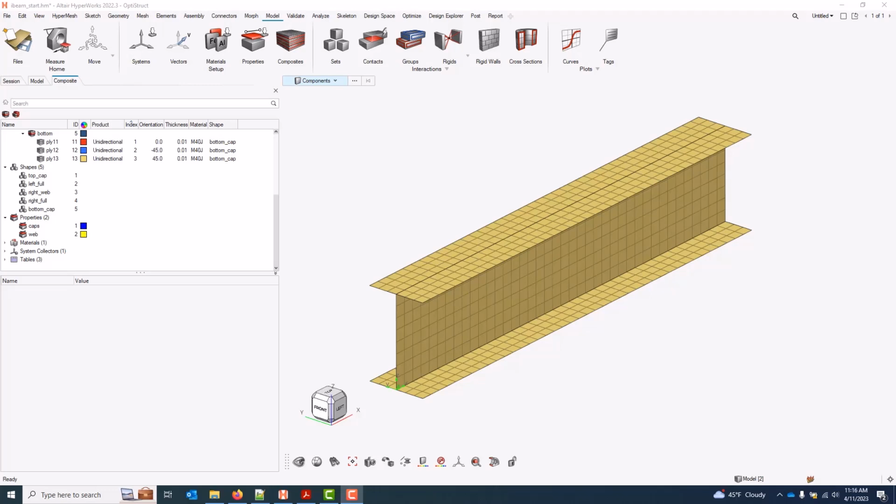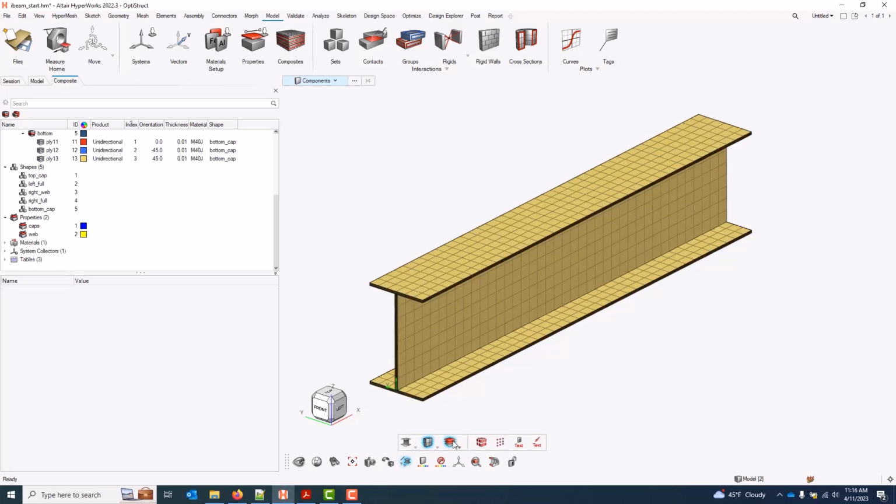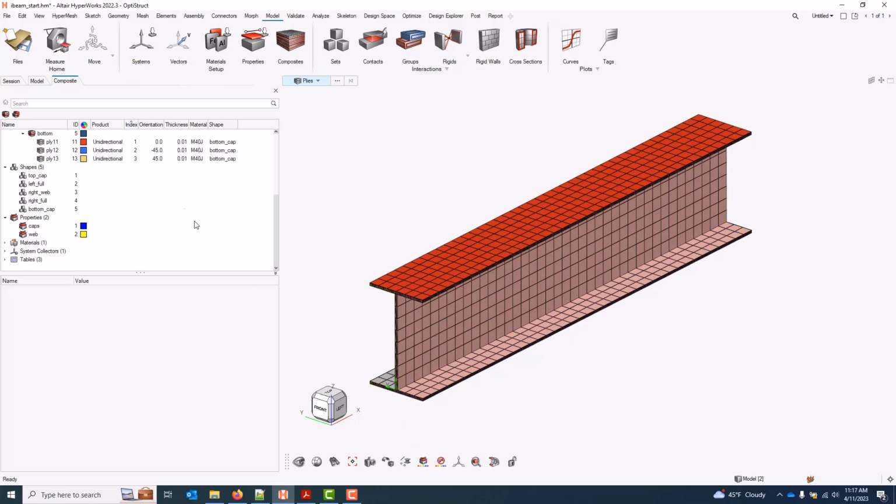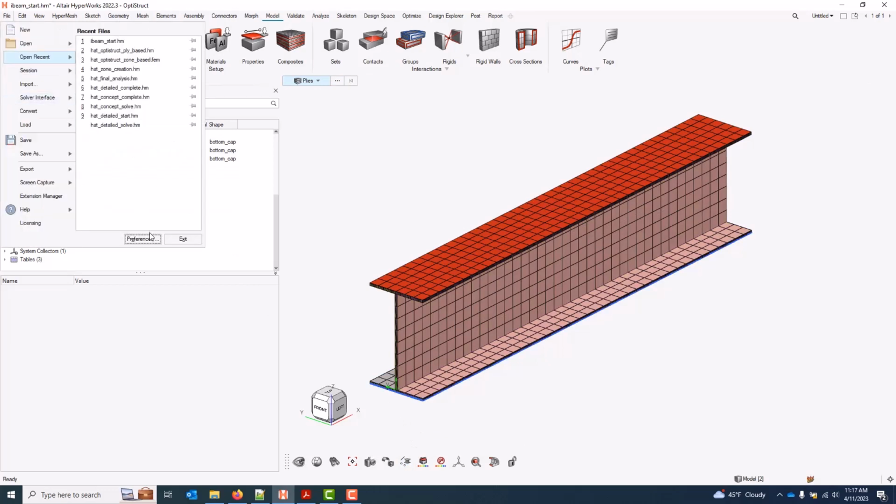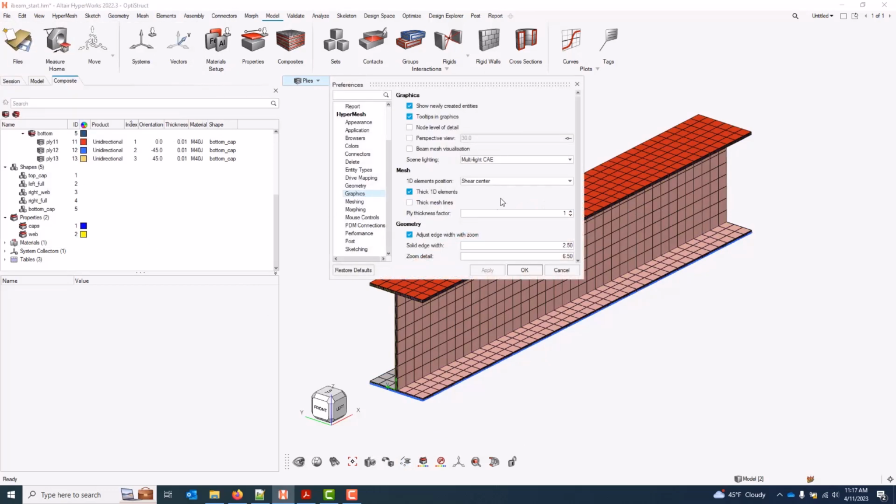This video covers visualization for interface laminates. In particular, to verify that my bookkeeping is correct and I input all the specifically interfaces and ply normals correctly, I like to use 2 visualizations. The first is a detailed thickness view with ply layers turned on. And I'll go ahead and just scale artificially the thickness a little bit so it's easier to see.